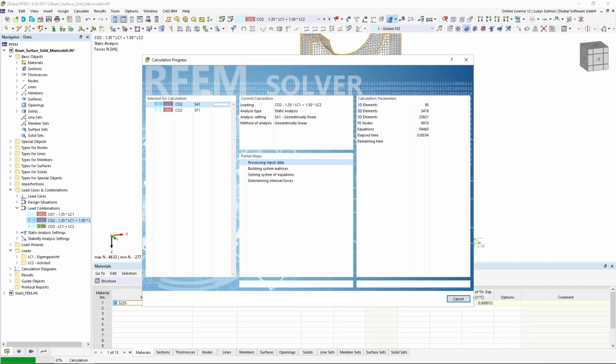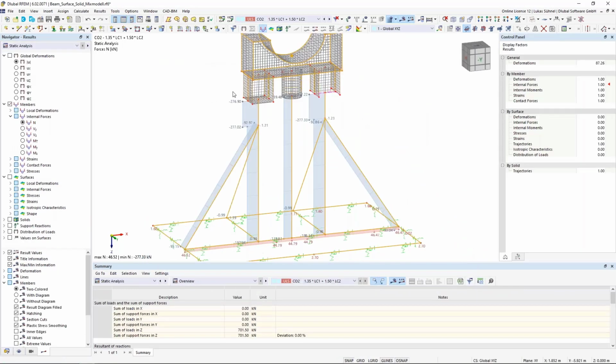So this add-on will calculate this critical load factor. It will also calculate buckling lengths and buckling length factors. For me, important is now only the critical load factor. And again, if that is bigger than 25, then buckling is not an issue. Just a few seconds more. All right, there we are.